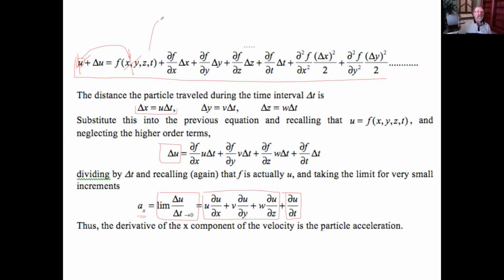Let's go to the previous case. We had a tube. And the flow goes in. And then the flow comes out. But because of that, we have to apply a force F to keep it in place. But F is equal to mass times acceleration. So it turns out this is steady state. Everything is steady state, but this flow turns. Therefore, the particles do have an acceleration, which are these terms.